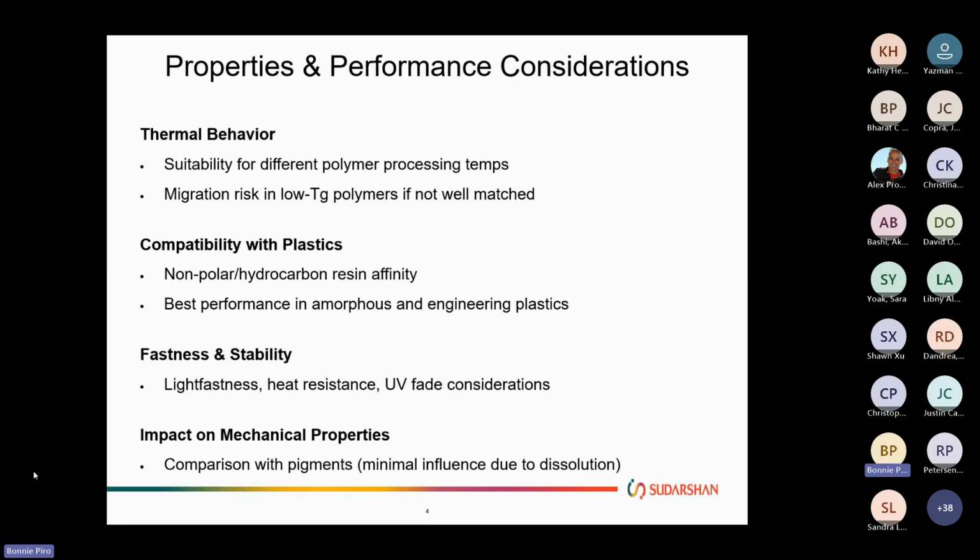Some additional things to consider. We've already mentioned suitability. In some cases there might be a migration risk, especially if the polymer in use is a lower Tg polymer. So you always need to match the solubility and the polymer together.